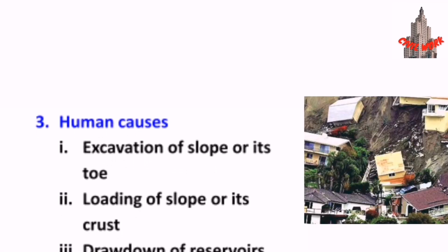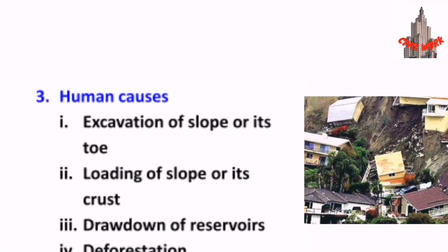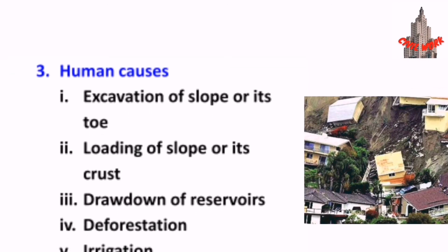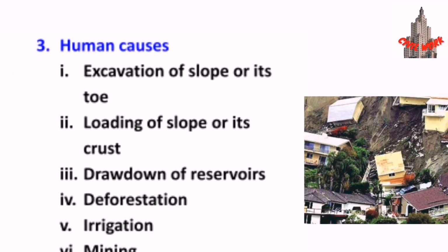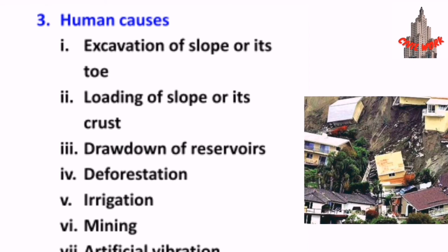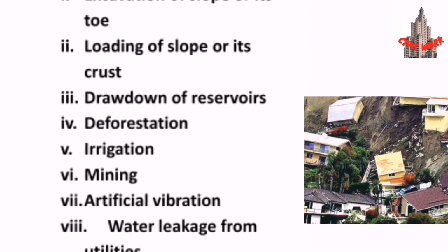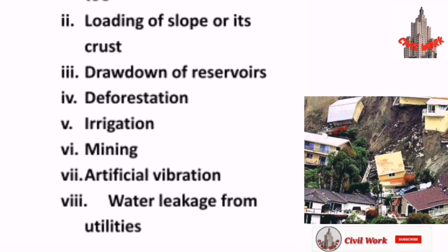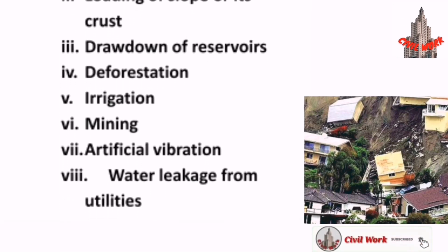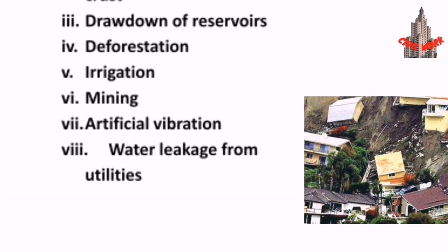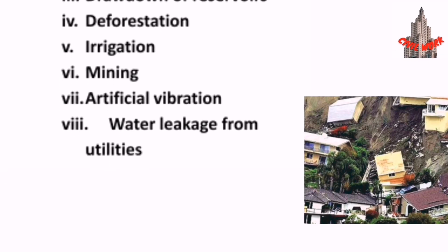3. Human causes. 1. Excavation of slope or its toe. 2. Loading of slope or its crest. 3. Drawdown of reservoirs. 4. Deforestation. 5. Irrigation. 6. Mining. 7. Artificial vibration. 8. Water leakage from utilities.